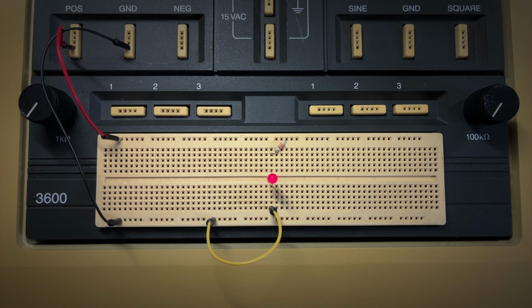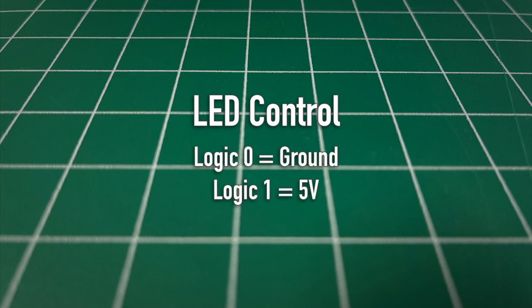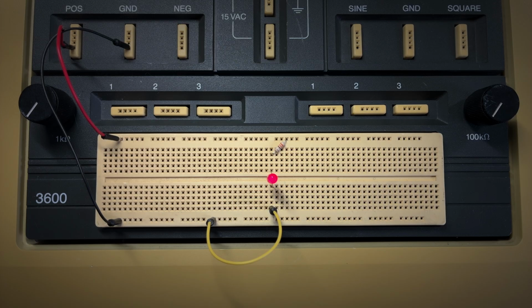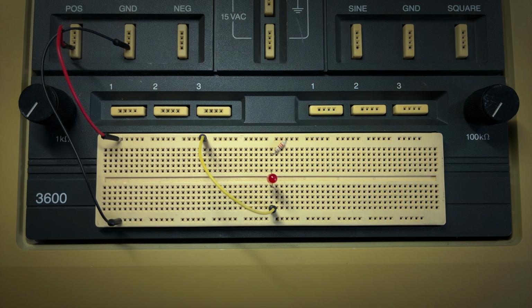Simple. But how could we turn this LED back off? Well, one option would be to disconnect the ground wire, like so. But in a computer logic circuit, that's not the normal option. What we need is to control the state of the LED by sending either a logic 0, ground, or a logic 1, 5 volts, to the cathode of the LED. So a logic 0 would be the ground connection we currently have, and a logic 1 would be moving the wire over to the same 5-volt rail that the other leg of the LED is attached to.